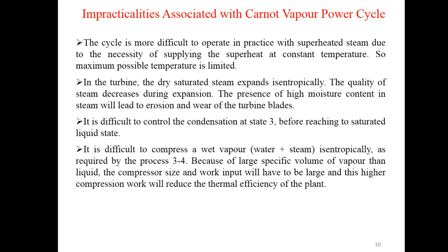Next is impracticalities associated with the Carnot vapour power cycle. The cycle is more difficult to operate in practice with superheated steam due to the necessity of supplying the superheat at constant temperature. So the maximum possible temperature is limited.